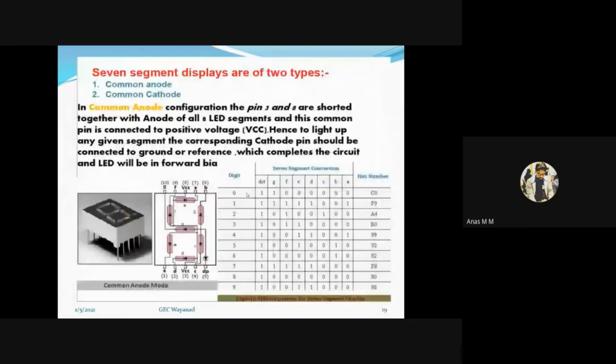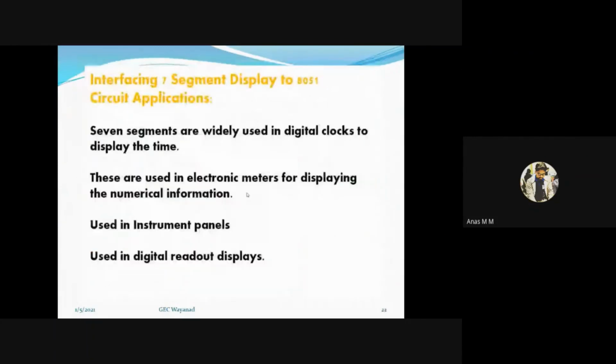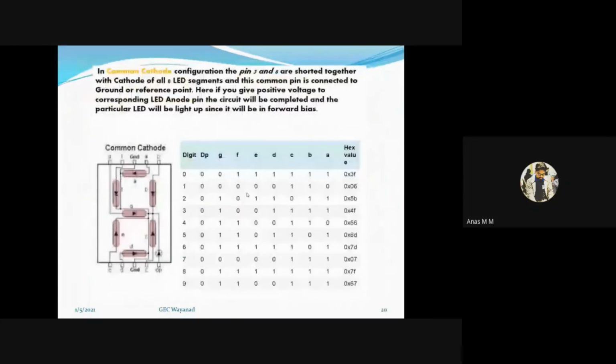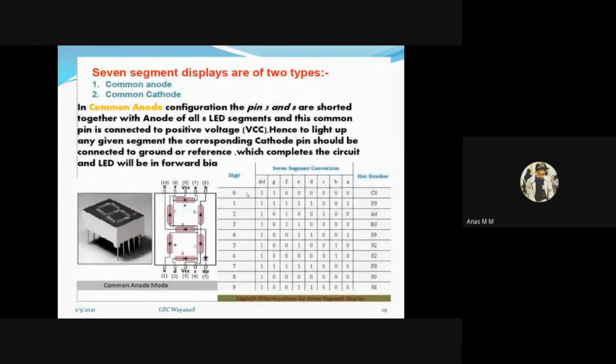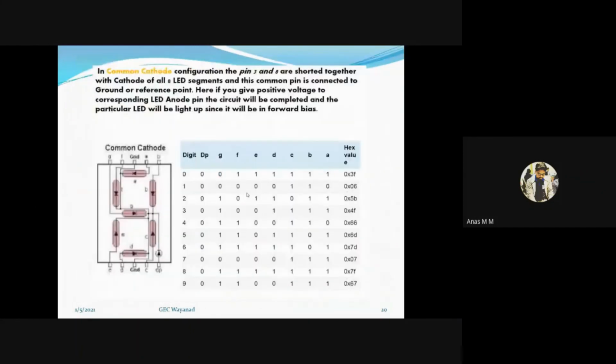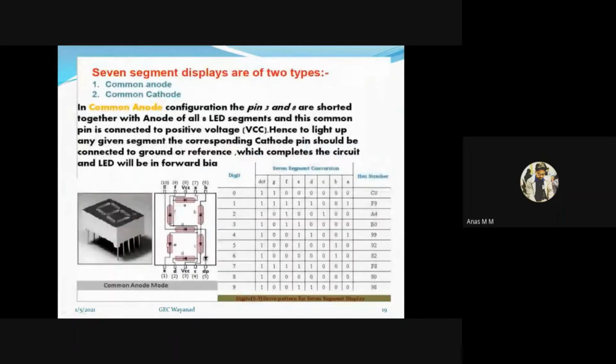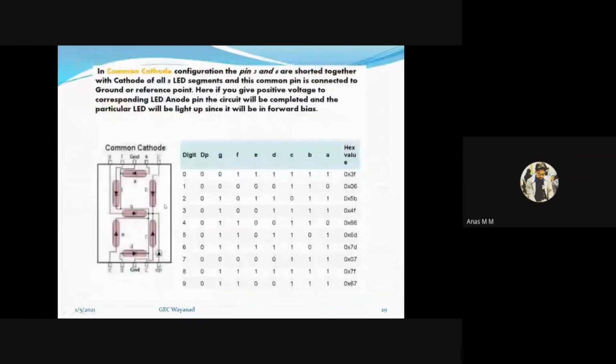Okay, now this is the state machine I created for common cathode configuration, where we are connecting peripherals to the positive terminal. That is why we are putting 1. In the case of common anode configuration, we need to connect a negative value to the hardware. That means wherever we need a high value, we need to copy 0. So the opposite value.